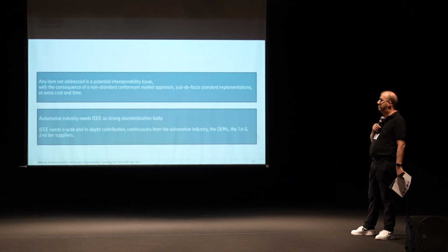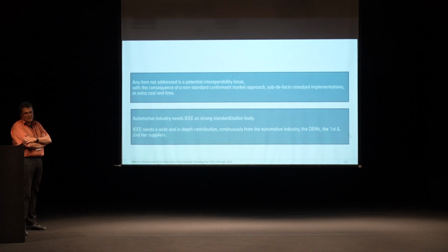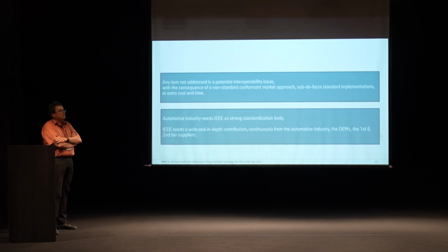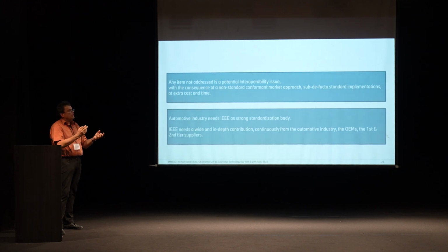Yeah, I've mentioned it here also. I think it's always a critical state when you have to change the mode from a stable operation to a silent mode, to a more low power consuming mode. The circuitry is changing, you change the state, and it might be critical for bringing some noise on it.